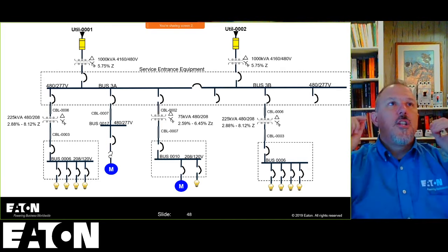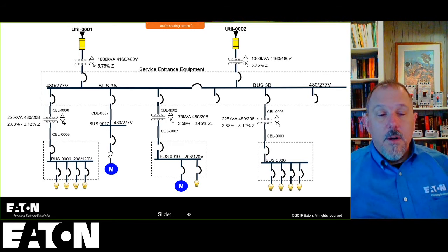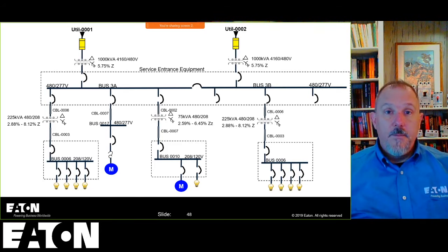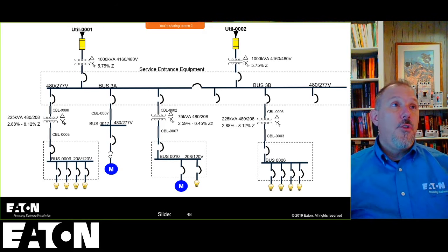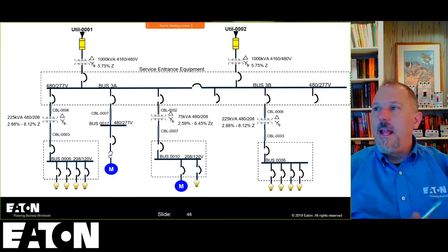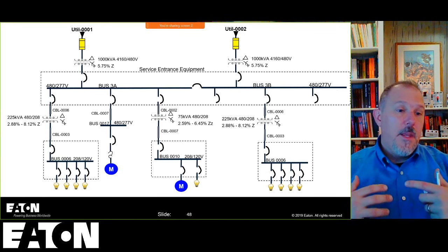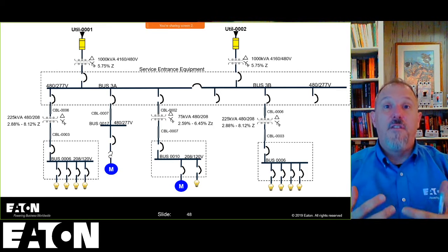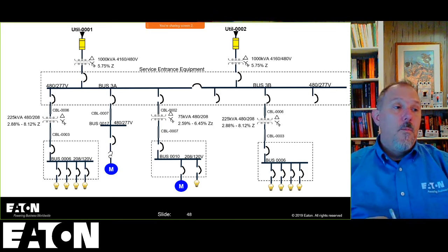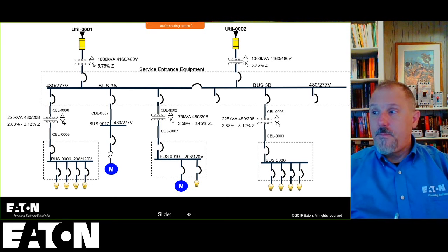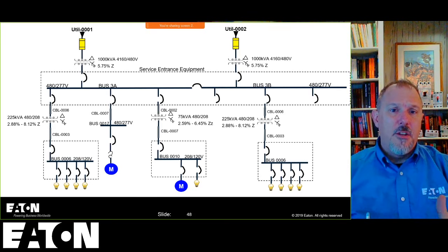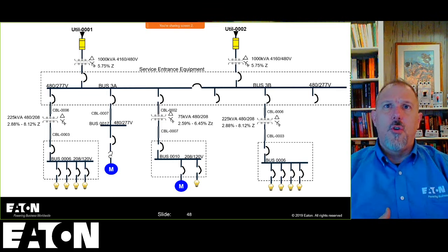Now, I mentioned turn all the motors off. Well, yeah, you could do that. Is that realistic? Probably not, right? So you've got to make things realistic, because you can end up just creating labels that aren't realistic and puts guys into 40 cal outfits, and that in itself creates a hazard. Overdressing for a situation is not the greatest thing either, because you're restricting the movement of your electrical workers, the tools they're using, and all of this stuff.